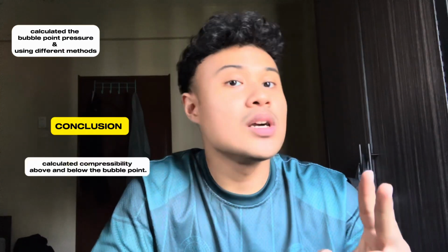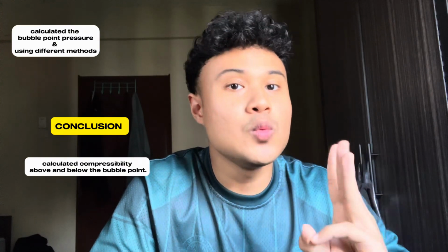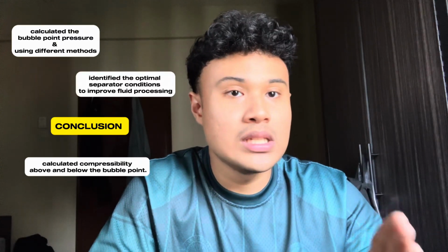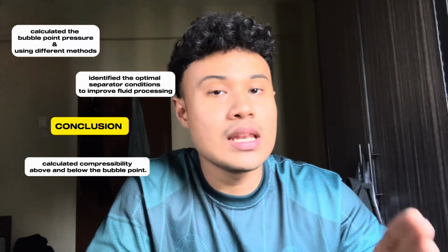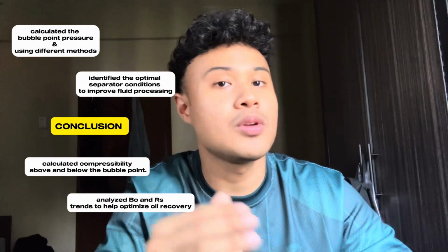To wrap it up, here's what we did. First, we calculated the bubble point pressure and confirmed it using different methods. Then we calculated compressibility above and below bubble point. Next, we identified the optimal separator condition to improve fluid processing. And last but not least, we analyzed Bo and Rs trends to help optimize oil recovery.